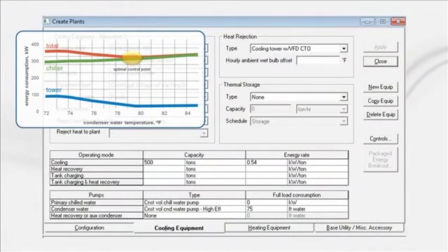Within Chiller Plant Analyzer, all that's necessary is to copy the base alternative, then select the same cooling towers with chiller tower optimization control. Now, we considered putting the chiller evaporators in series, but since the customer oversized them significantly in this job, the second chiller doesn't run very often, so it probably doesn't fit for the application.